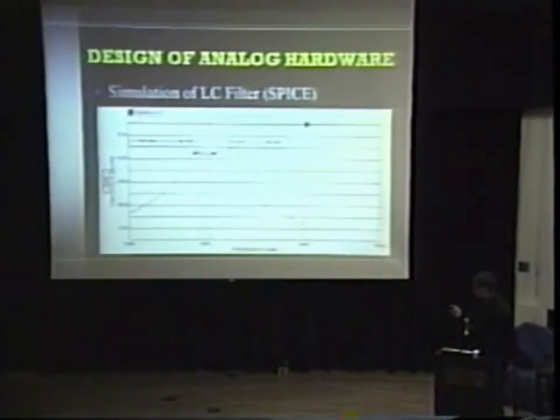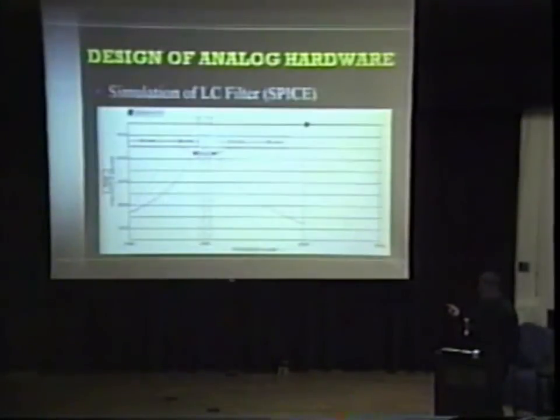This is the output of the bandpass filter using the values that I was able to achieve in the lab. There's a small 0.2 dB ripple that you can't see in here. It's minor and isn't a requirement for this system because it's frequency modulation; the amplitude isn't a factor. But as you can see, the bandwidth of this system is the tracking bandwidth of the demodulator, which is 40 kilohertz. The bandwidth is from 180 kilohertz to 220 kilohertz, with the mark and space frequencies being 210 and 190 kilohertz.